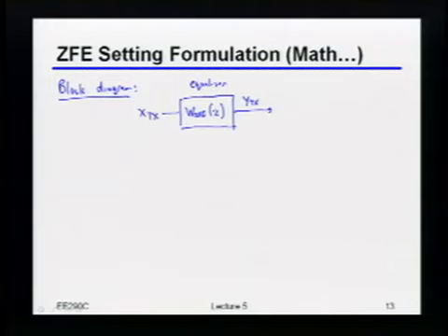Then that is going to pass through my channel. In this particular case, because we're working with discrete time, I'm going to sample the channel at the same rate as I sampled my data. So instead of a continuous time channel, I'm just going to sample it in the time domain, or rather in the Z domain, to get discrete sample responses. I'll show you how that works in a second. Coming out of that, I'm going to call this Z_RX, the analog received voltage. Is everybody with me so far?